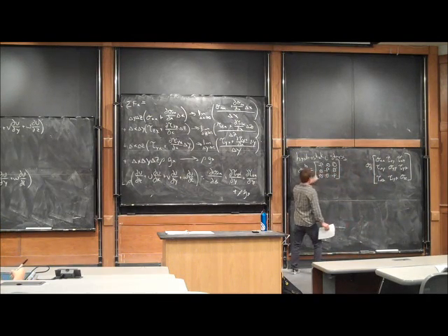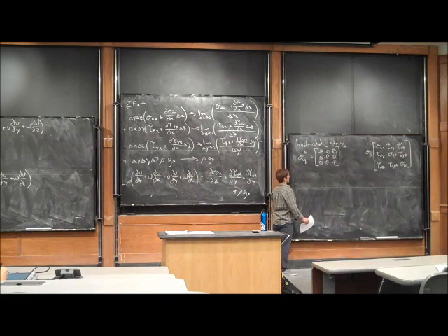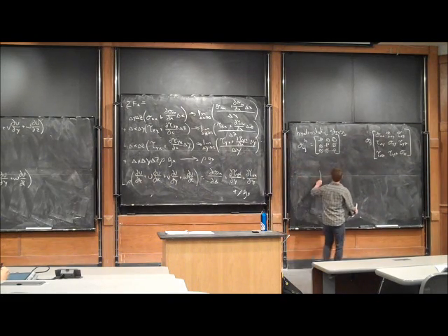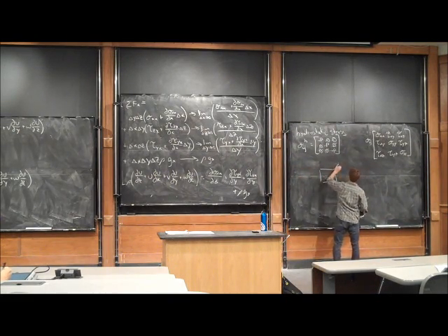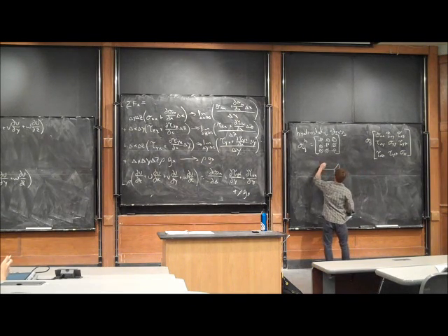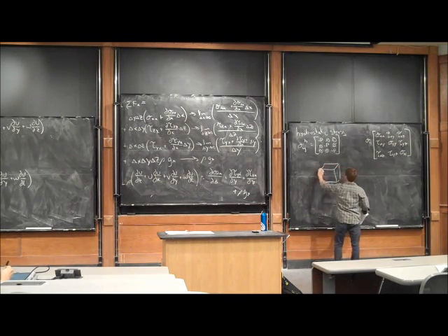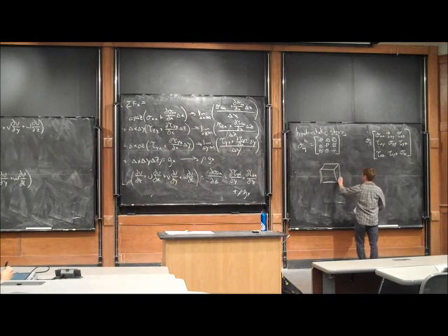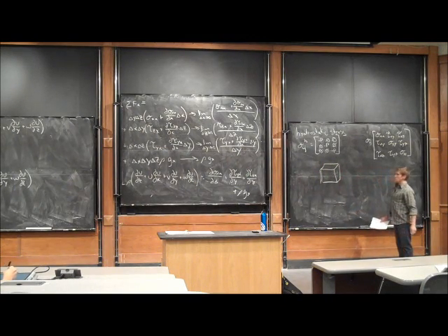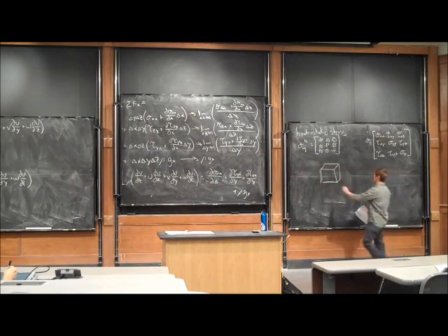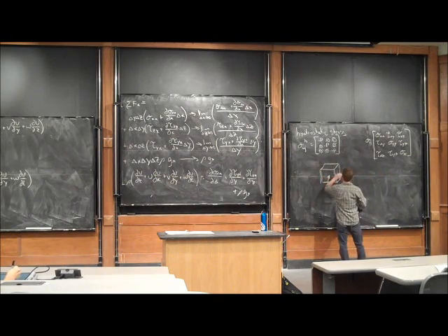Your hydrostatic stress: if I looked at just that fluid element, what would be the stress acting on it due to pressure? We only have three components because the pressure is always normal to the surface of the cube. So we have a P acting here, a P acting here, and a P acting here.